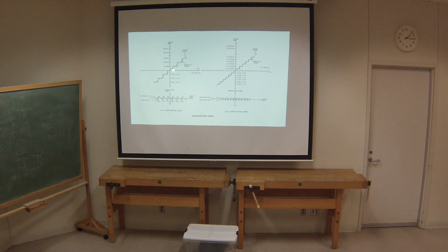Let's say we sample right at this point. Notice we're kind of right in the middle. Is it a 1 or is it a 0, right? Well, that's the question. Well, here the maximum error is gonna be what? Half a volt, one way or the other.